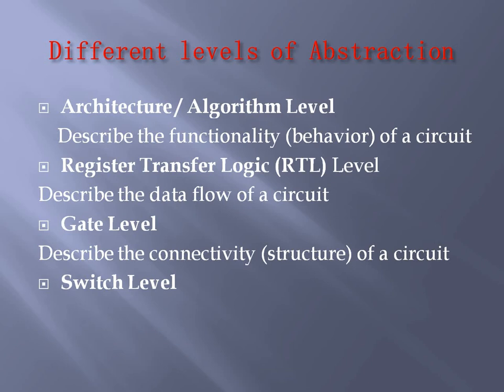So some of these models can be mixed up as mixed modeling, and sometimes we can even use mixed language. There are some languages which I'll tell you in the next slide, where we can mix up languages and describe the design or functionality, which we call mixed language. But overall, there are basically three abstraction levels: behavioral, data flow and structural level.